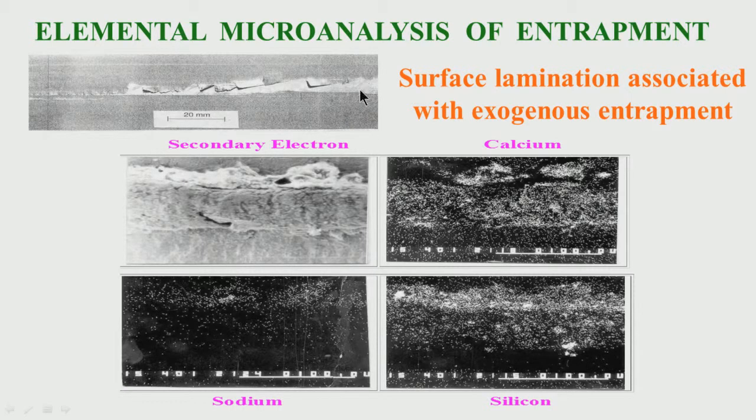So, you take that material, cut a small piece, put it under SEM, in secondary electron mode, not the normal image mode, and you will see this defect has been magnified.